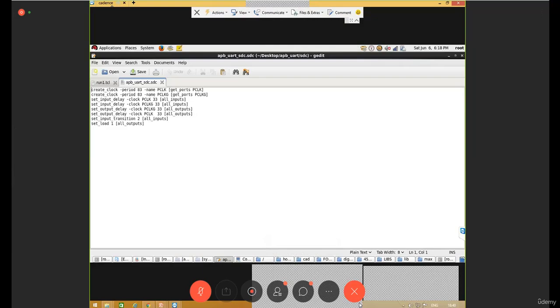Here, as of now, how the time budgeting is done: the period is 83 nanoseconds, right? I took 40% of the 83 nanoseconds for the input delay, and 40% for my output delay.